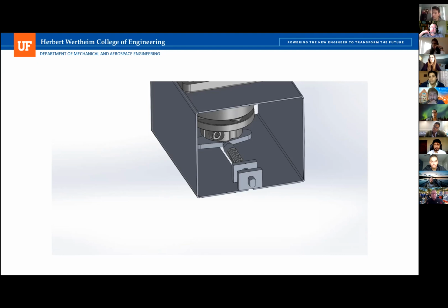It's kind of difficult to explain without pointing at things. So maybe a channel for the rod to sit in as the cam is rotating around the outside of it. Well, no, it's not so much that. It's more the angle of attack. If this cam was a perfect circle, imagine a wheel with the rod, that's your ideal in terms of contact. It doesn't necessarily provide the movement that you need, but the ideal is a circle where, as you turn the circle, the rod smoothly glides along the outer edge of the circle.